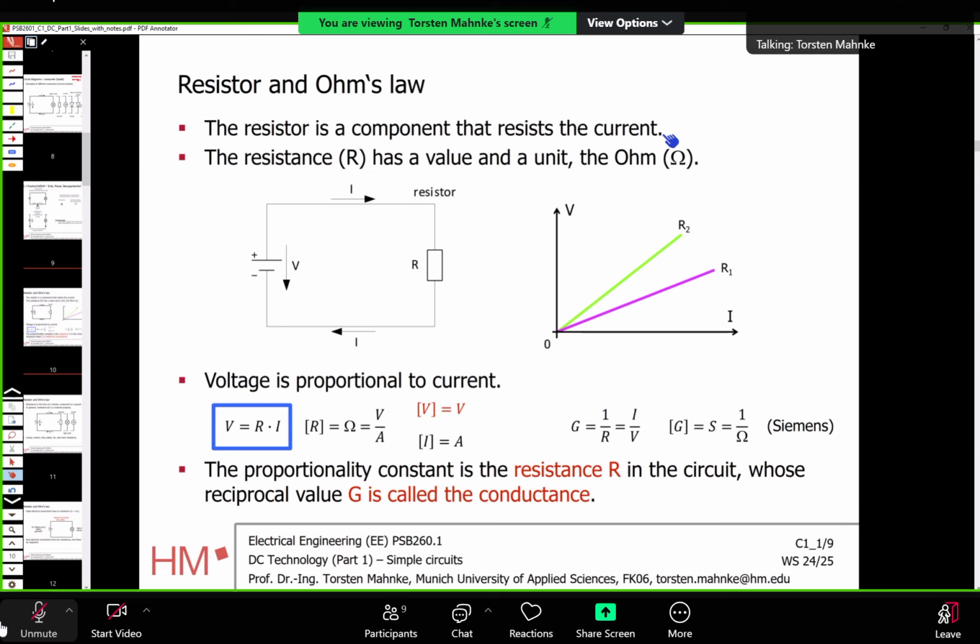So when you do this with the normal standard little 1.5 volt batteries that everybody knows, it may not be that bad. They become hot and it takes some while. If you realize it early enough, maybe nothing happens really, but I wouldn't try it anyways. But if you do it with a lithium polymer accu, let's say from a remote controlled car or something, they have really high performance accumulators in there, and you create a short circuit, I think you have a good chance to burn them. So be careful with that. A short circuit is never a good idea.